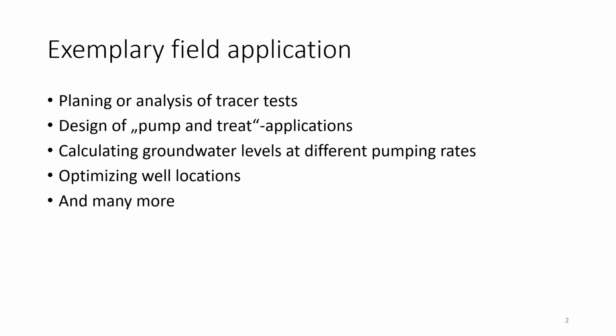But maybe you want to know, assuming some kind of flow velocities, where it is best to install my observation wells, or how far the tracer will travel, how it will maybe distribute in a heterogeneous subsurface. That's where simulations can help you, for example, to plan the tracer test, or when you have the results of the tracer test, you can try to simulate the same experiment and try to understand what kind of conditions caused the observed results in the field.